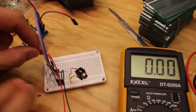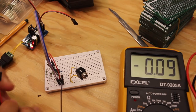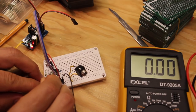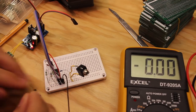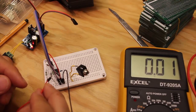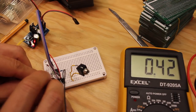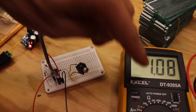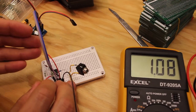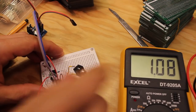And let's make some measurements here. Let's begin with the voltage divider. So here we have ground and plus 12 volts. Then we have the voltage reference input, and there we have added a voltage divider with these two resistors. So this pin 2 should read 1 volt, and that is because we have 100k to voltage plus and 10k to ground. That ends up at 1 volt.